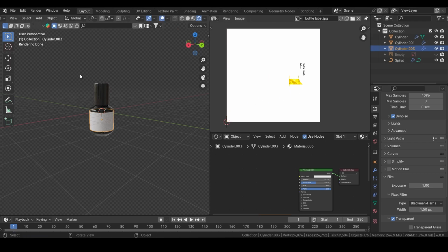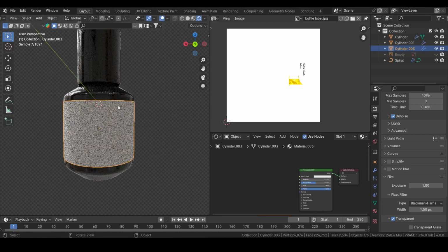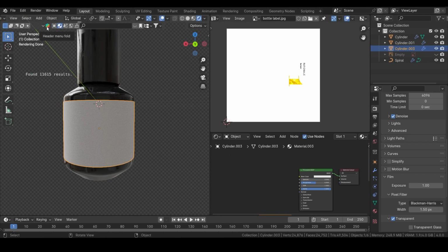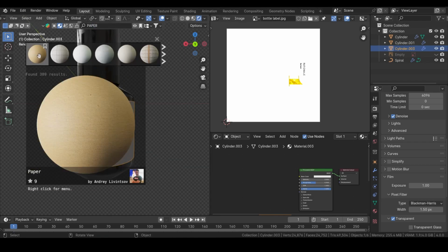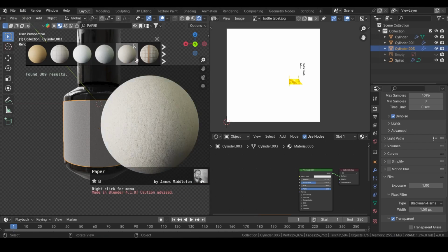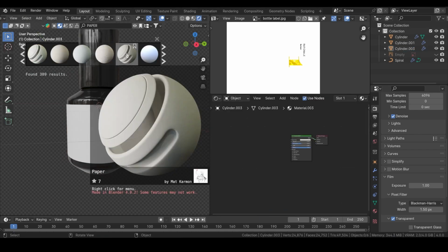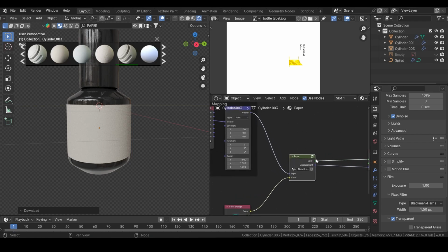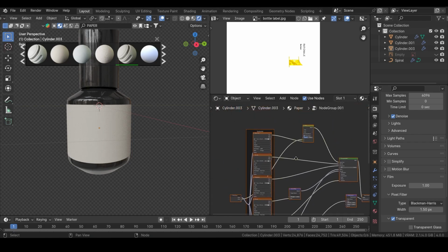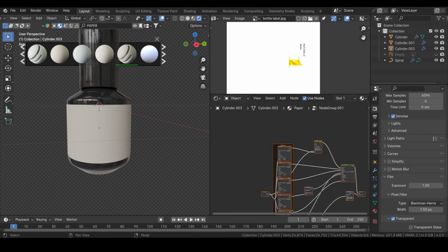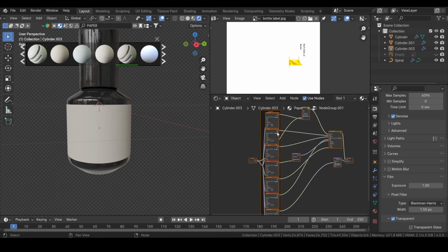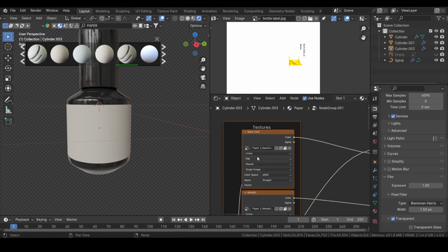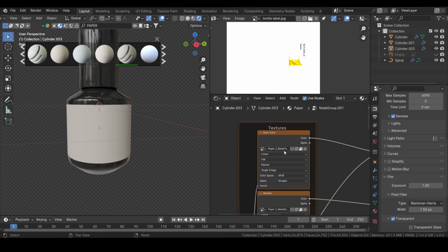But the thing I usually do with paper textures, this is where you don't necessarily have to do everything on your own, I just go to Blender Kit and search for paper and look for one that has subtle wrinkles. This one looks like it would do the job, so we just drag and drop this on the material. We get this. If we go into the object group, we see all the textures. So it has a roughness, metallic, displacement, all of them. So we just need to replace the base color with the branding I already made.